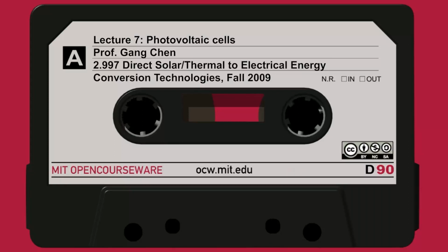That's where we stopped in the last lecture. It's about comparing the PN junction, a diode, with a Schottky barrier. You can think about on the left a Schottky diode, on the right a PN junction. And when you look at the current-voltage characteristics, it's very similar, right? Except that the coefficients are different.